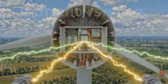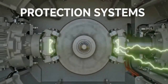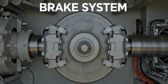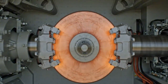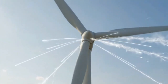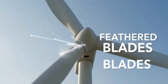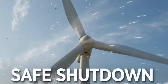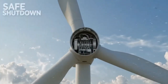Cooling air moves through vents and ducts inside the nacelle, helping electrical and mechanical equipment avoid overheating. When conditions become safe again, the turbine can slowly return to normal operation. The blades leave the feathered position, the rotor accelerates again, and the generator begins producing steady power.